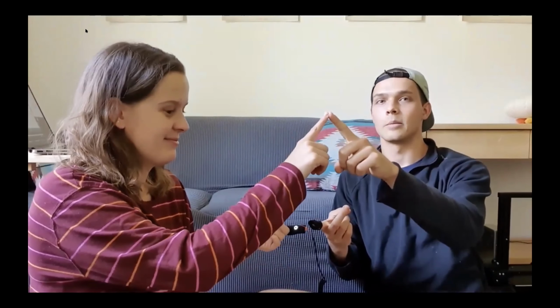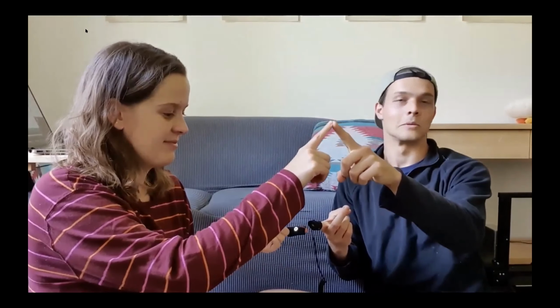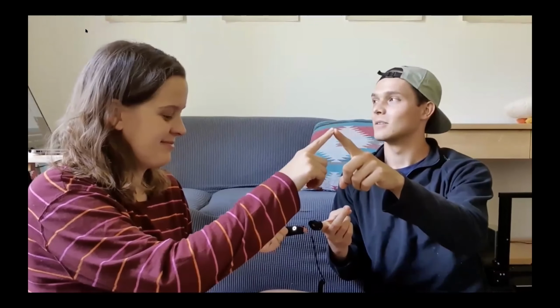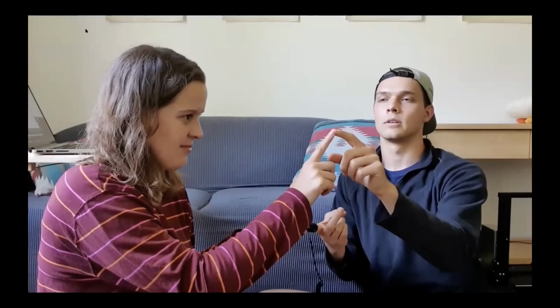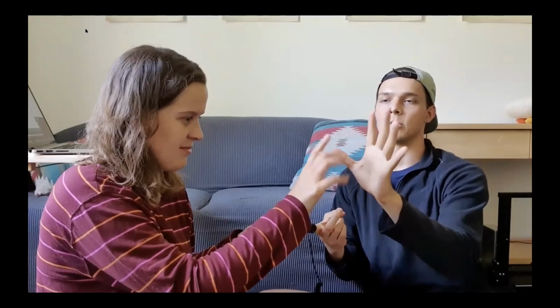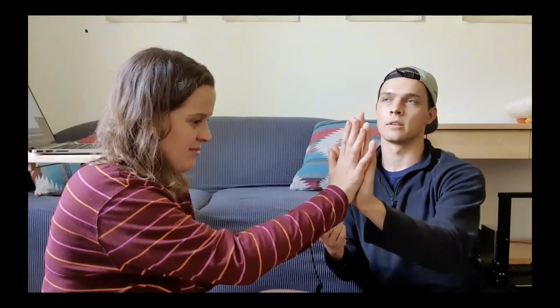But then the idea is the sensor I'm using is a galvanic skin response sensor. Ordinarily, you want both electrodes on your own skin, and then as you hold your breath or you are frightened, the capacitance of your skin changes. But in this case, we're putting one electrode on each of us so that when we touch, we will generate pitch at the capacitance of our total, I guess, skin capacitance. So it's going through our skin. So this is a tap, and then the more surface area, the lower the pitch.